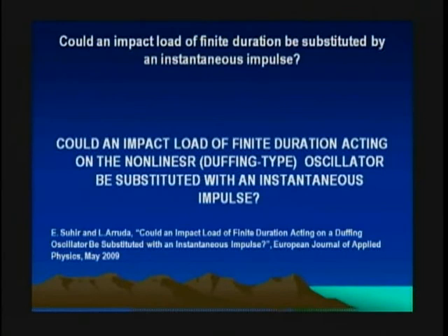The other problem associated with nonlinear vibrations that I already mentioned to you has to do with whether you can substitute a shock load of finite duration with an instantaneous impulse, and we came to the conclusion that you always can do that in the linear system if the duration of loading doesn't exceed 1/8 of the period of vibrations. But even if the duration of loading is as significant as 1/4 of the period of vibrations, even in this case, the error is not very much.